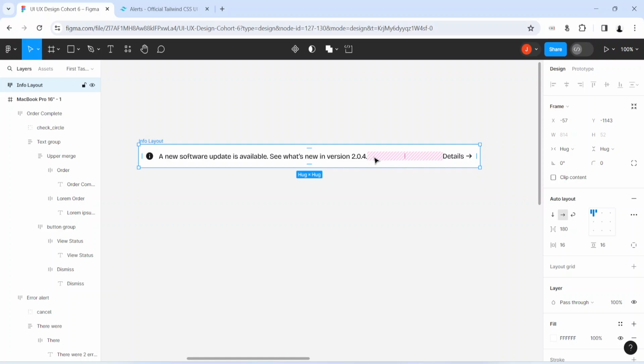So I don't want to define a space between them. I don't want to set a fixed space between them. I want the space between them to be automatic so that it will always push both of them to both ends, one to the right, one to the left. That space is called an automatic space. It's called an auto space.